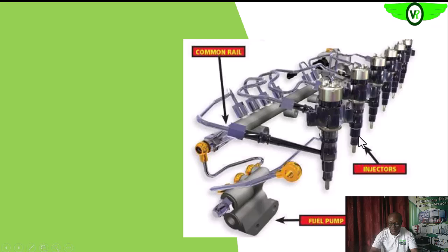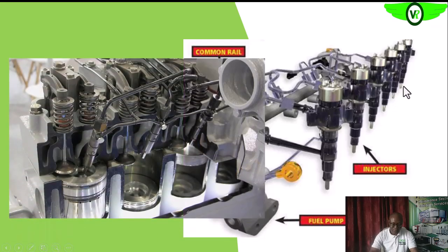So these nozzles are connected to each of those cylinders. As you can see here, see the nozzles in the cylinder, okay. So when the piston, as we'll see later, has been driven to the top dead center, the fuel will be injected, okay. At that point it will be combusted also, so the force or the energy in the combustion products will force the piston down. So that downward movement, the translational movement, will be converted to rotating mechanical motion by the crankshaft, as we said earlier. So this is the arrangement.